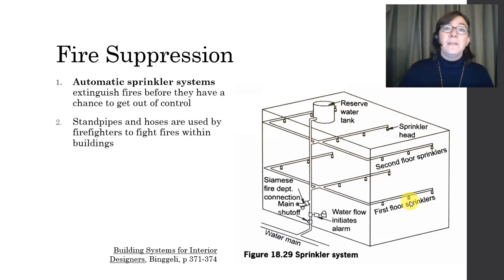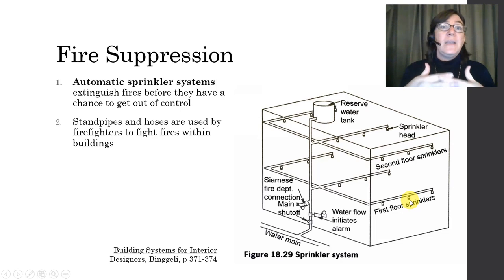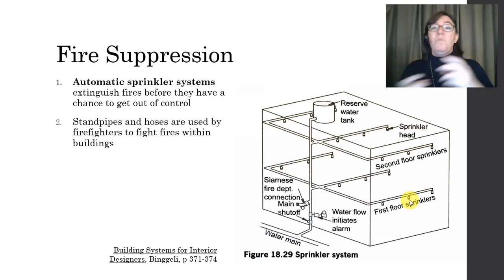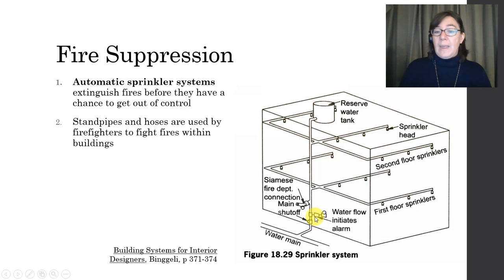So we talked in the last slide about detection and noticing smoke, flame, or heat. Well, these sprinkler heads themselves are heat detectors. They will activate when they get too hot. And the flow of water through the system is one of the ways that will initiate a fire alarm.